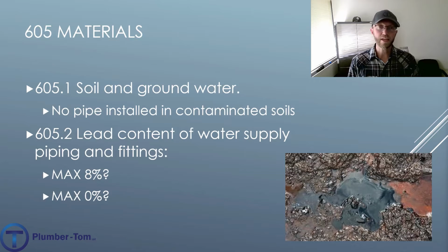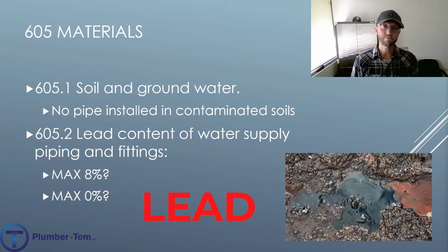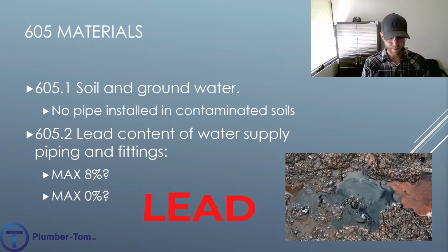Speaking of contamination, there are a lot of four-letter words out there, but one of those is lead. That's become a very bad word because, well, I guess we've come to understand that lead poisons the brain, and nobody wants that. So lead content in water supply pipe and fittings is very limited. 8% is the most that it can contain.